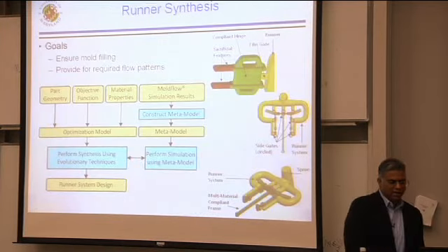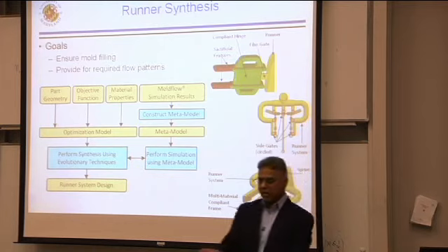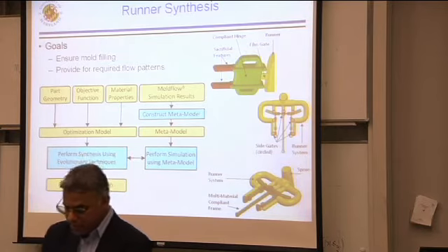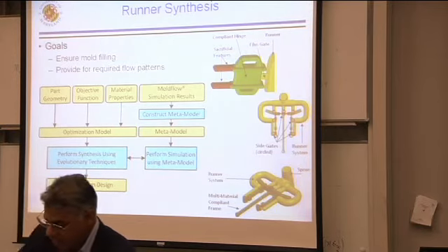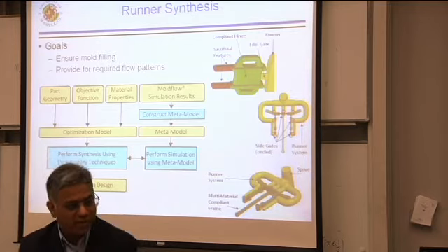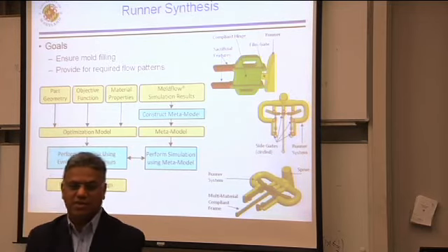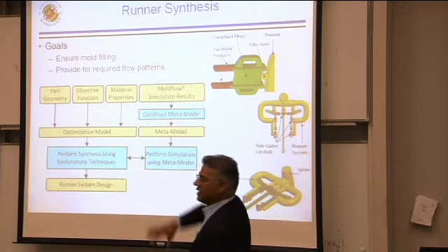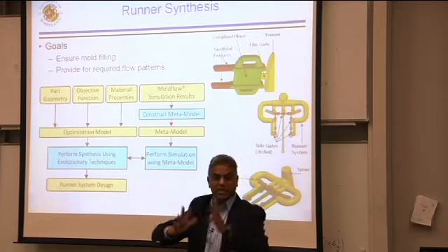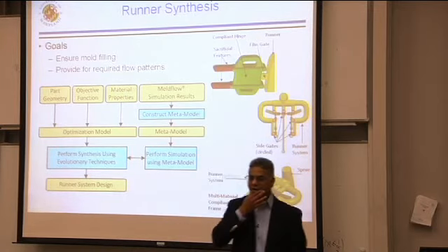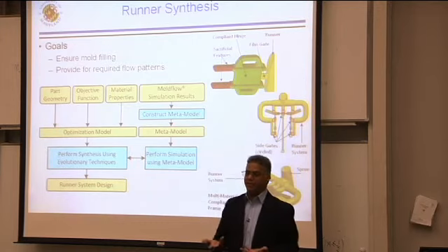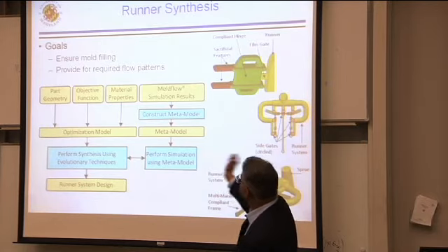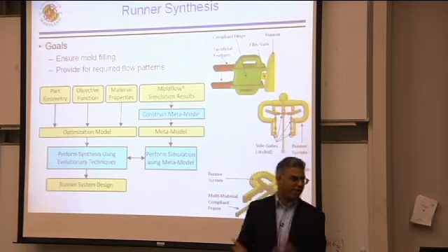So you do that. And then it turns out it's a multi-material molding problem. Runner design becomes a very complicated problem, because this tiny thing is sitting in the mold, and if you inject it with a polymer, and the two polymers coming from two sides don't meet at the right time, this thing gets pushed to the side, which causes all sorts of problems. So you have to synthesize a runner which gets all the timings right so that this thing is going to survive. Unfortunately, for in-mold assembly there are not that many good runner design tools out there. So we had to build our own runner synthesis tool to work on this problem. So we did that.